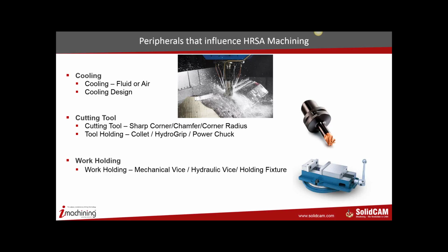Should it be a sharp corner end mill? Should it be a chamfered end mill? Because today there's a fad amongst cutting tool vendors to provide chamfered end mills that they say reduces forces while cutting and improves the life. Or should it be a corner radius tool? All these put together, we need to make an informed decision.